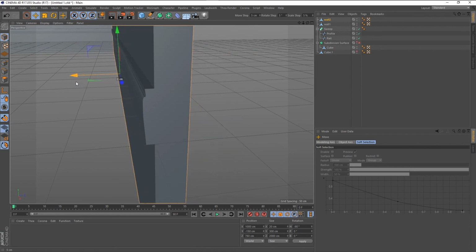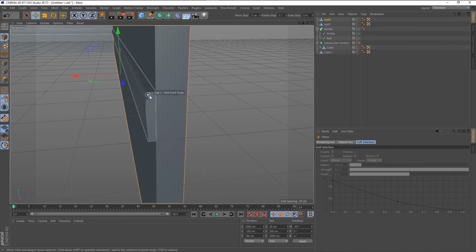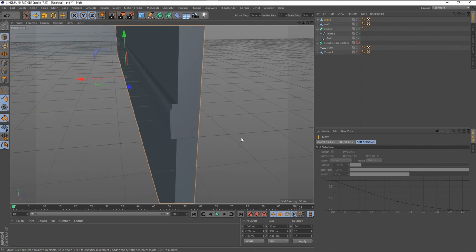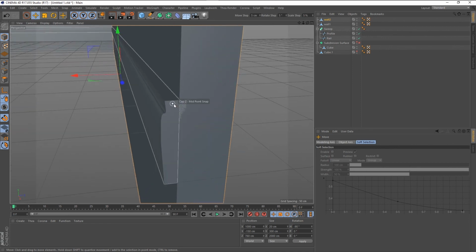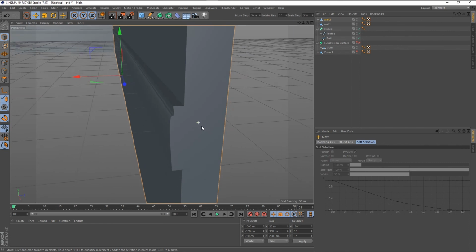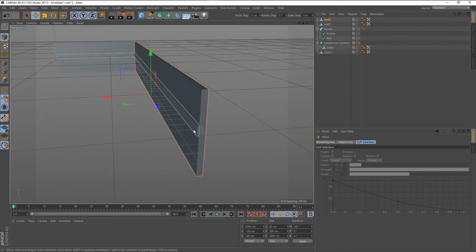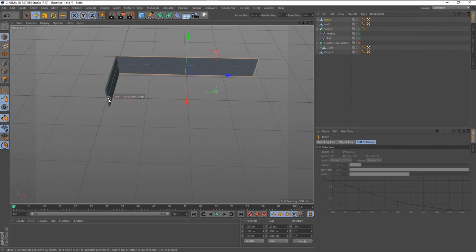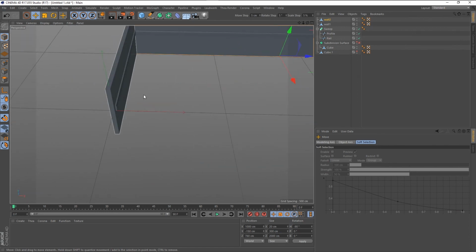So what's nice about that is that the wall base is intersecting with the wall, and that's what you want. You don't want to have two surfaces share space in 3D coordinates. It causes errors in the render engine. So this is what we do.